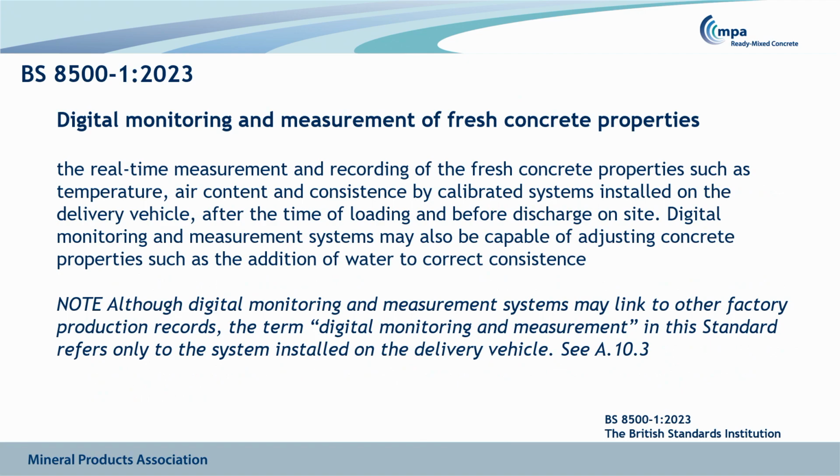Digital monitoring and measurement of fresh concrete properties. This has certainly been in a lot on LinkedIn recently, with the requirement on HS2 for these systems to be fitted by trucks. These are the real-time measurement and recording of fresh concrete properties, such as temperature, air content, consistency, and so on, by the delivery vehicle. Now, when this was written probably 2 years ago, we were introducing this concept as an idea that it may start to replace identity testing, not realising that contracts such as HS2 would actually start to use it before we published the standard.